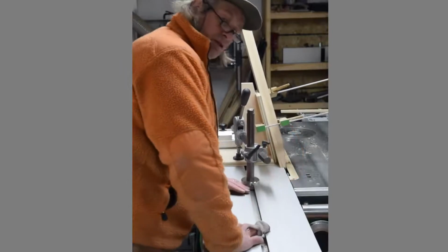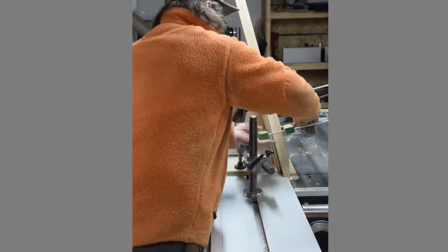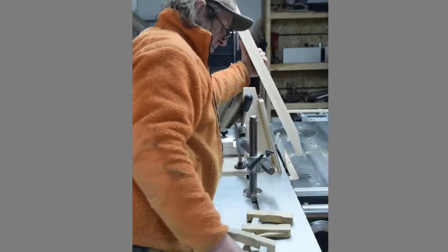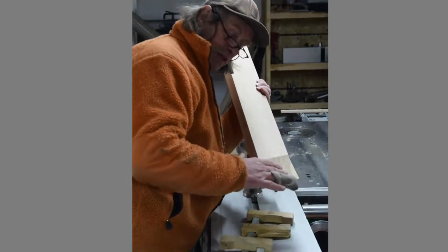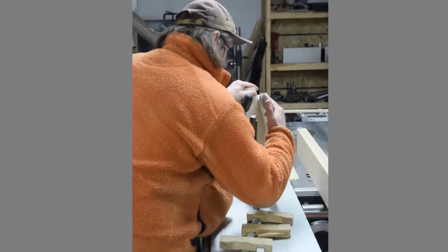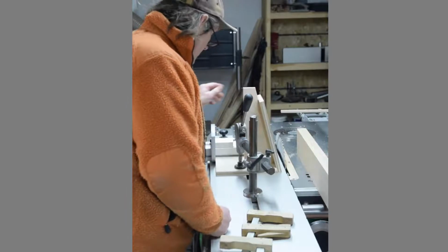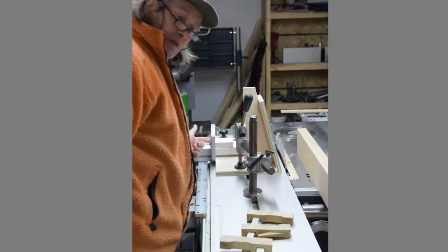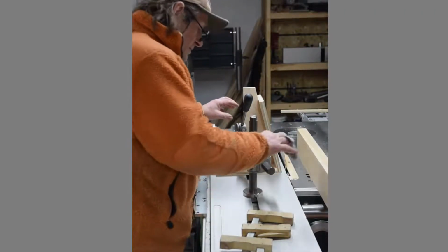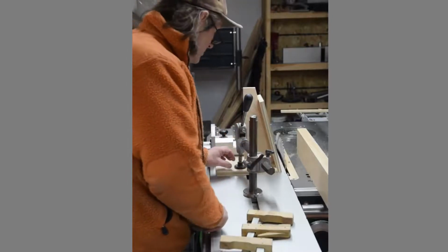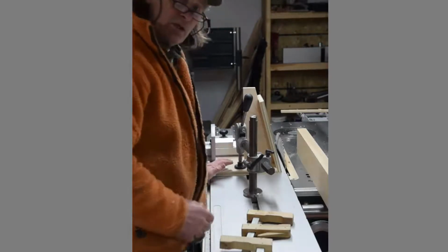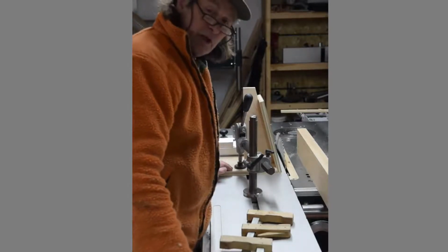I push it through the saw blade and I reverse the whole setup now. So I take off the leg from the jig. Here you see the flat surface I just cut. This is the jig here. It's angled 13.5 degrees back. The stop is adjusted in position in that direction of the whole jig, and this huge clamp makes sure that the jig is firmly clamped to my sliding table, and that's how you can safely do this, and very precise.